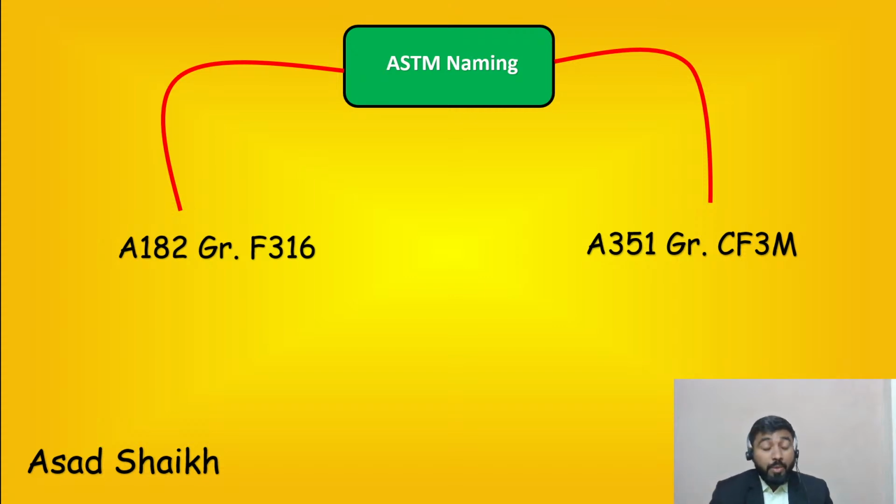As an engineer, why I stressed this point is, I would not name, but after talking to a few vendors, there are certain companies that, for a certain valve material, want it to be forged. So if the vendor has given the cast version of that valve body, it was rejected at a very late stage. So the vendors must be very cautious.